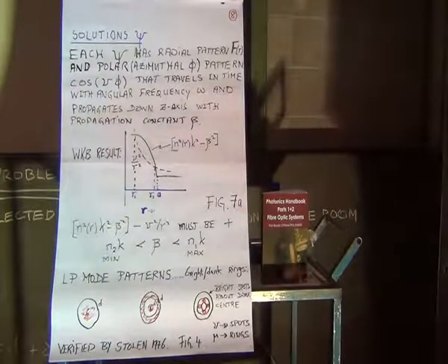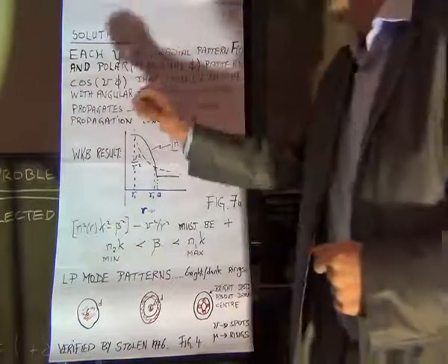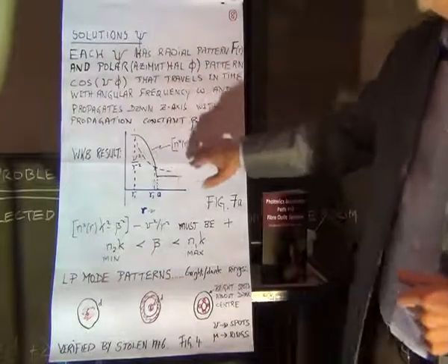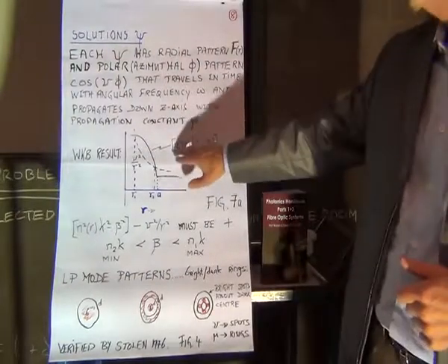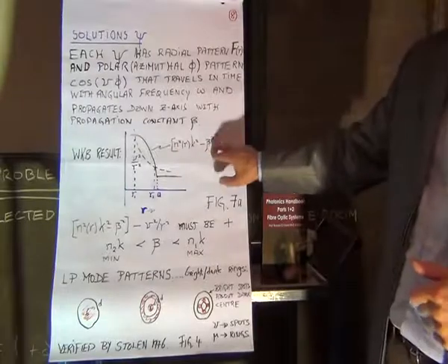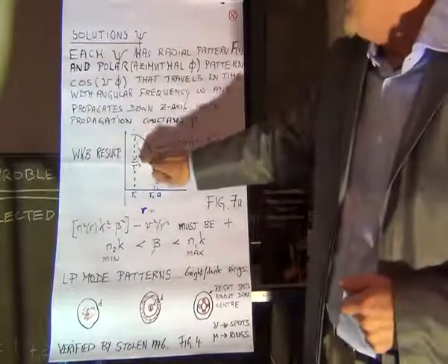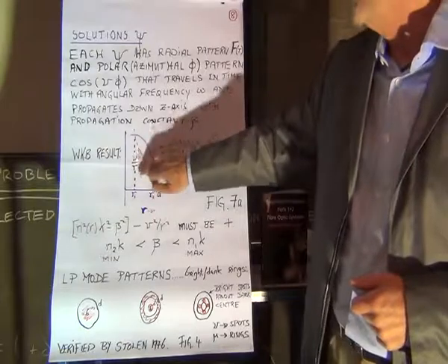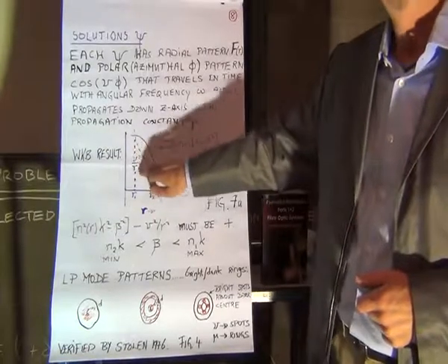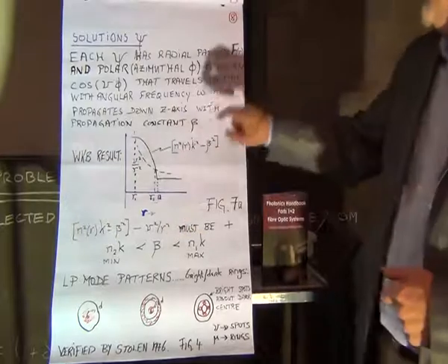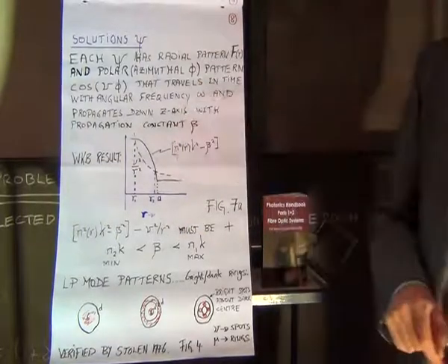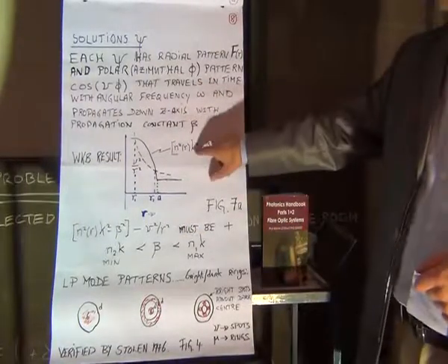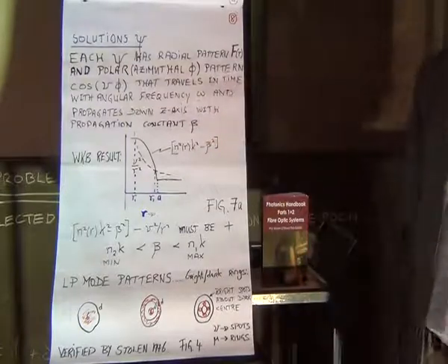So to get standing waves, it turns out that this jumble of parameters that comes out of the differentiation, n squared k squared minus beta squared, must be bigger than this. This came out of differentiating the cosine, the nu, and then the nu again. All right? n of r is the refractive index profile. k is just 2 pi over lambda.